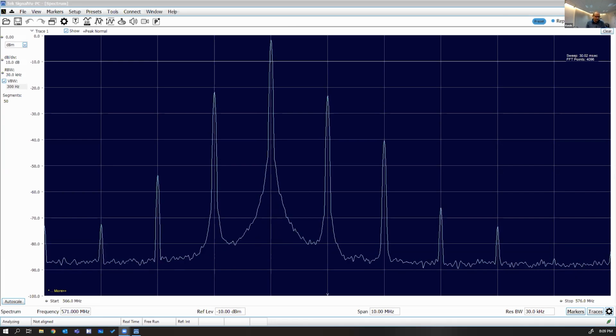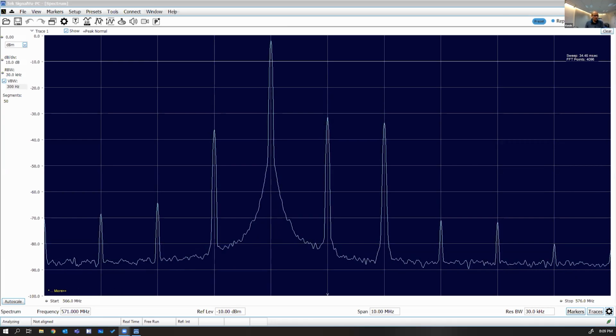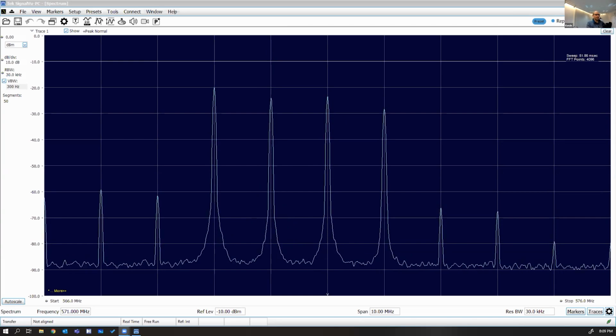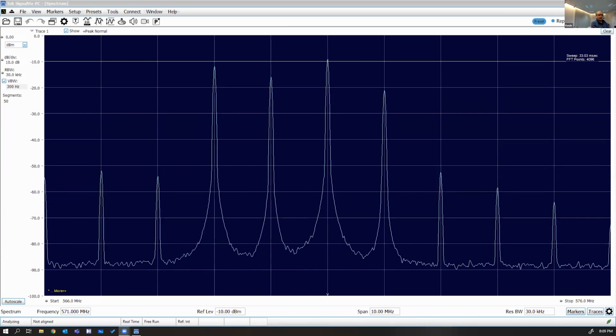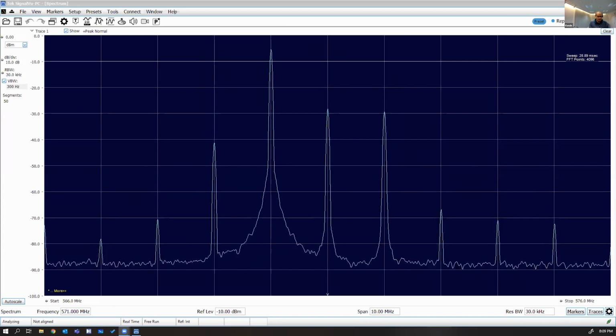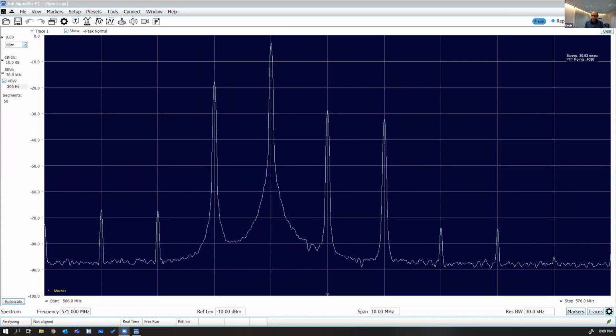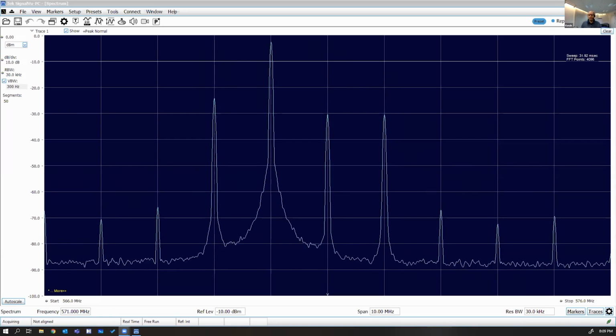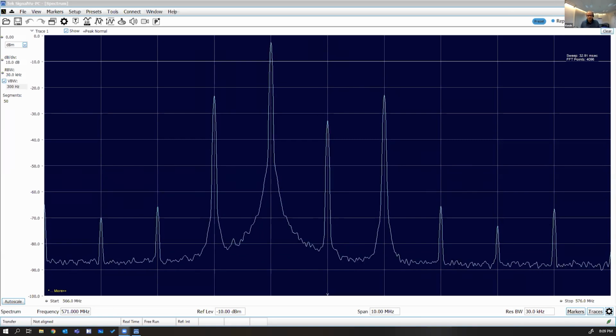So I have now 4 carriers. I'm going to take them all in my hand and go a little bit closer to the antenna, and you see basically what happens. You create many, many other carriers, which are basically then unusable for you. This is the traditional way of an analog FM system. This is the reason why you have to calculate frequencies. You have to find the spaces in between those carriers, in between those intermodulation products.